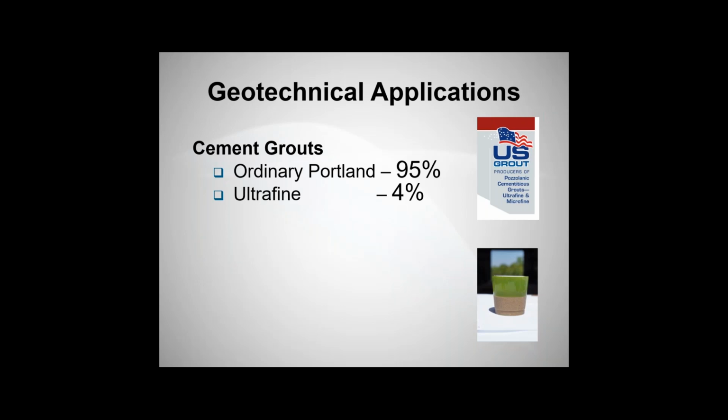Those are three grouts within that ultrafine family, if you will, typically hovering around 3 microns on average size. Microfines are 8 microns. Superfines can be as low as 1.5 micron, but predominantly that only gets used about 4% of the time in geotechnical applications.